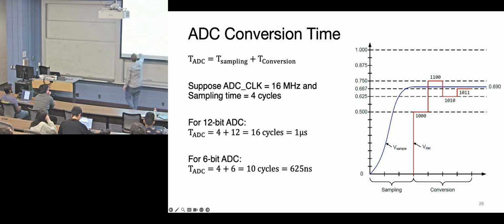And then this is just showing you the trick. Because it's a SAR ADC, you can choose to converge faster, converge early. There's no advantage. You do all the conversions when you set it up that way early. So you could do it at 6, and then you're able to run the whole thing faster.